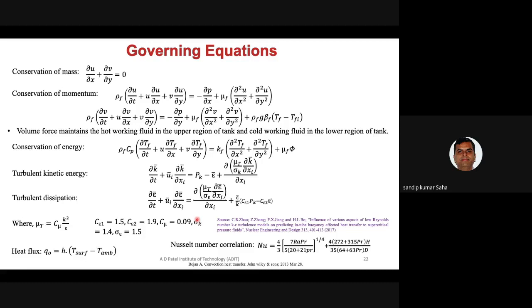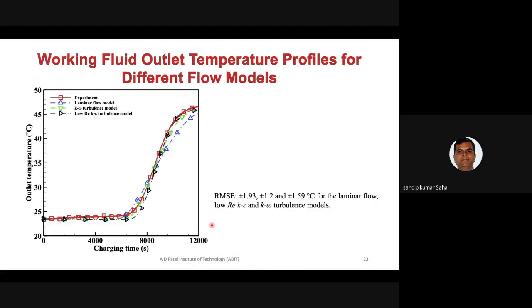So my next intention should be, okay, it is already done, now how I can actually validate my model, like whether the K-epsilon model is justified or not. So the next thing is the validation of my model always, because the same model you will be using for different situations. So now you have to always check whether the K-epsilon model is good, or the K-omega model is good, or maybe the Reynolds stress model is good. So how you will get that? Only if you do some experiments or get some experimental results can you compare your result.